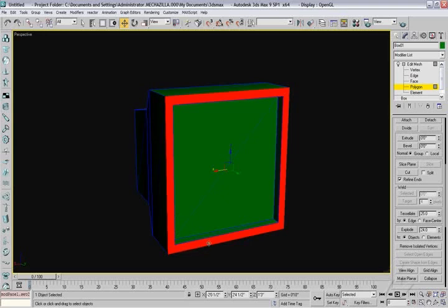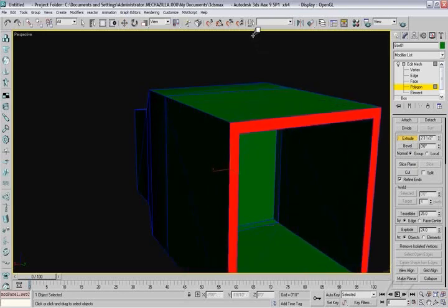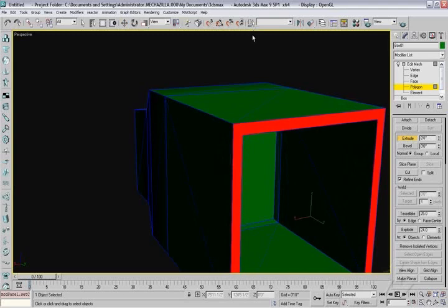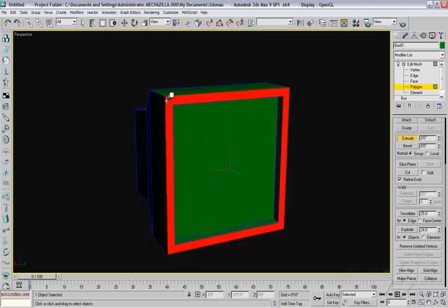Now, two things this supports. Again, if we want to actually apply a texture to it, where we have a visible edge is a cutoff range. Where we have an invisible edge, we'll apply it across that surface. Another thing it's handy for is if we want to continue beveling and extruding. For example, if I wanted to continue modeling, I could go into extrude and pull that out, or whatever have you. Now I of course don't want that, but hiding edges allows us to create custom geometry and shapes so that when we extrude from those surfaces, we can go from a square to an octagonal shape, which we'll get into in the next couple models here.